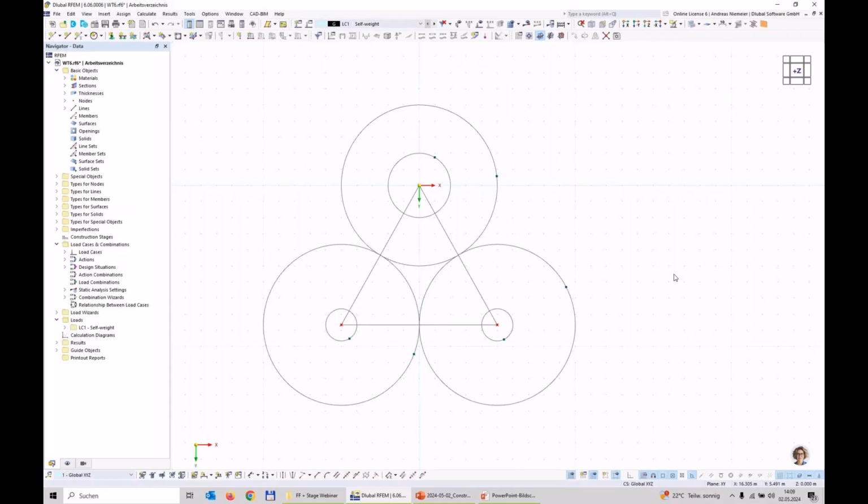Generally from drawing it's fine, but from creating a final element model, you will see that you get some node-oriented nodes like here, here, here, here, here. So if you expect later to have a nice symmetric mesh, it makes sense to orient such things.